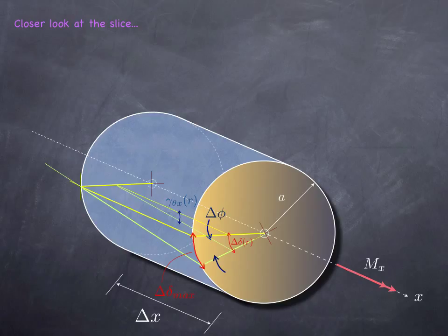We also know, as I mentioned to you before, that this delta delta of r will have its maximum value at the perimeter of the circle, as well as this shear strain angle gamma. So now we are ready to relate the displacement with the twist, and the twist here is simply the angle phi. I'll just call that the twisting angle or the twist. So I know that this line segment delta delta r can be computed by simply multiplying the twist angle with the radius at which I'm sampling this displacement, r. So I measured it from the centroid of the circle using that twist angle.